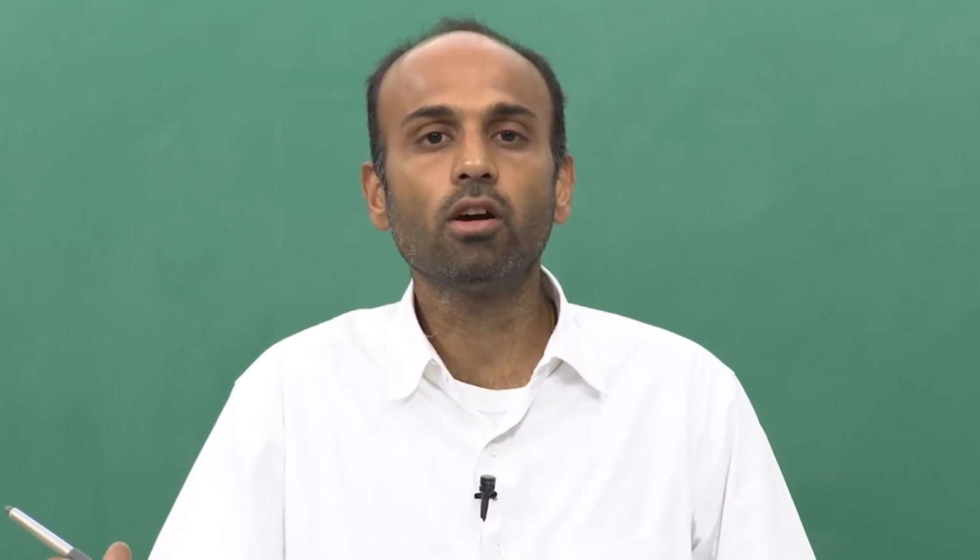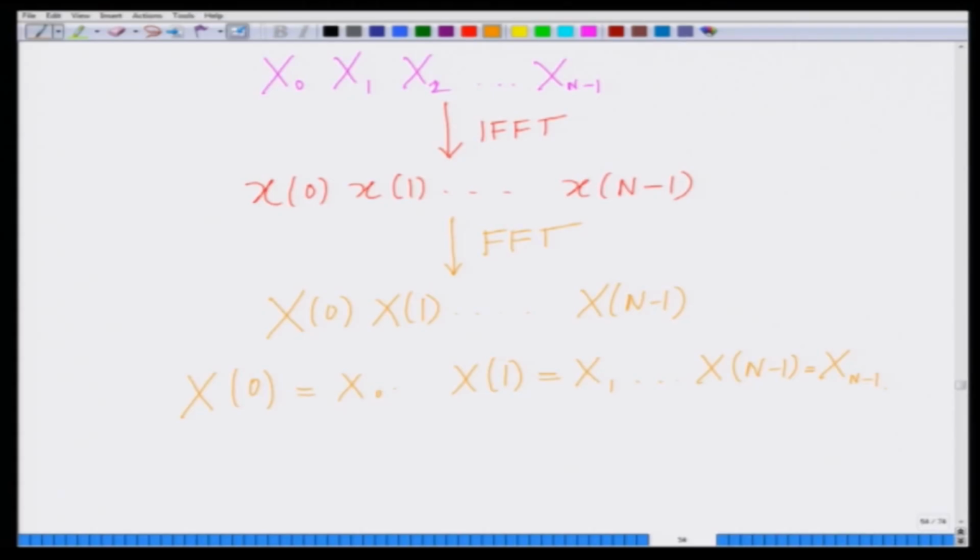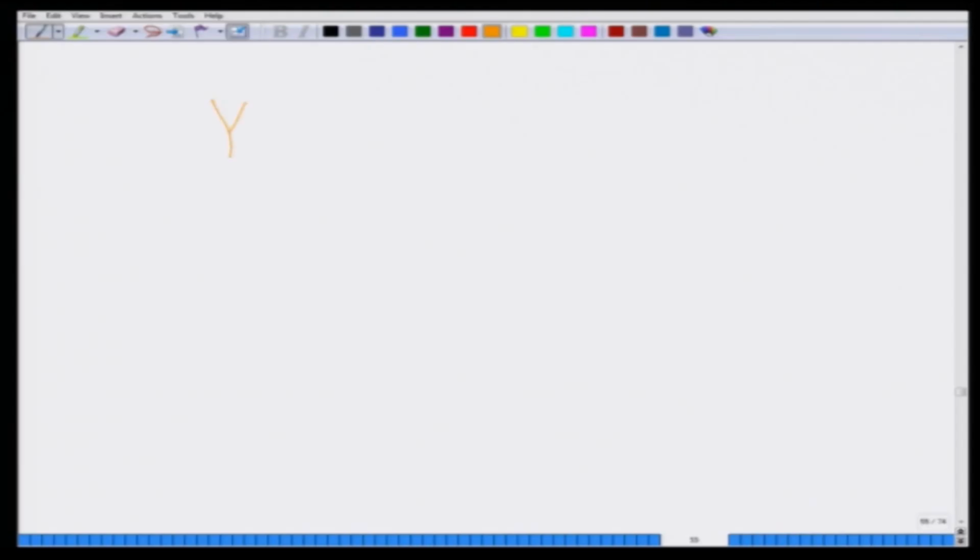Capital X sub 0, capital X sub 1, until capital X sub n minus 1, initially taking the IFFT to generate the OFDM samples, and then I am taking the FFT again. So, the IFFT and FFT cancel, and I therefore get back the symbols that are loaded onto each subcarrier. Therefore, very interestingly, what I have is Y_k in an OFDM system after the FFT,